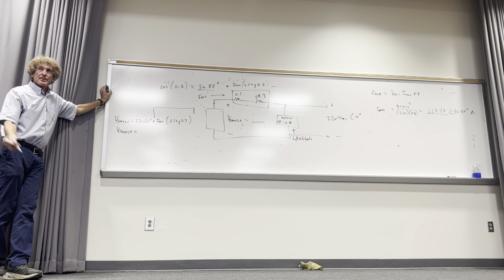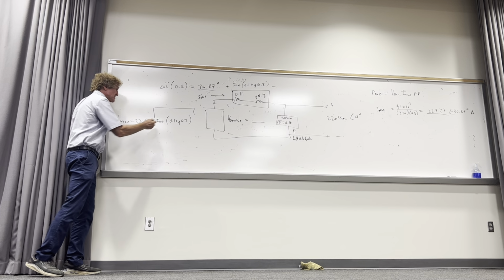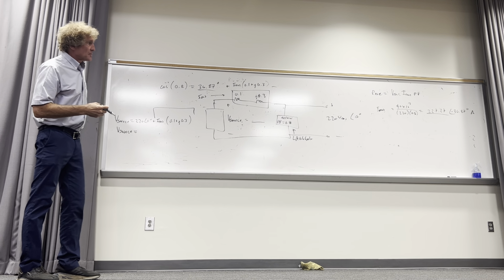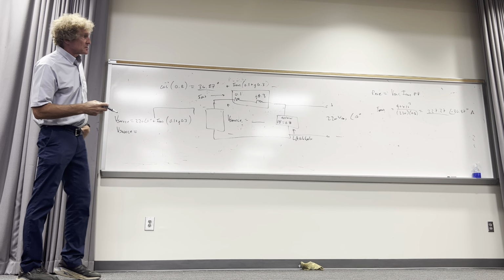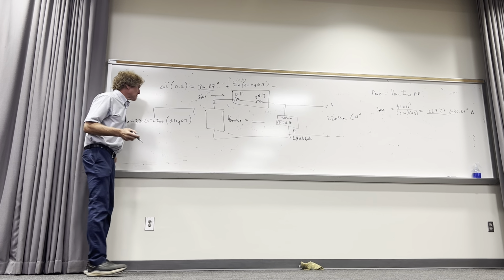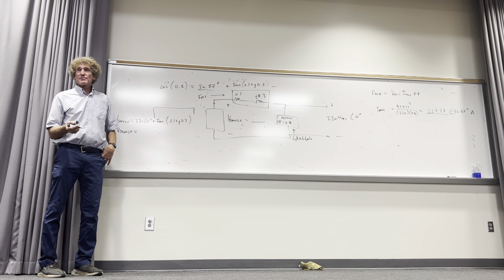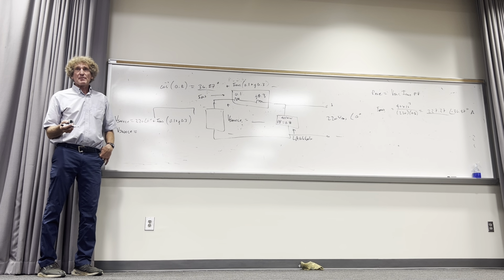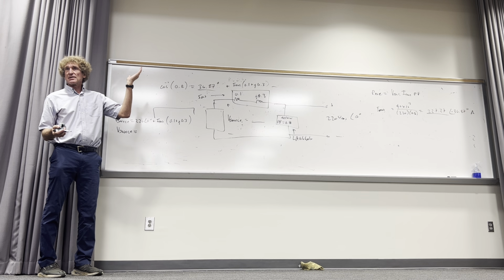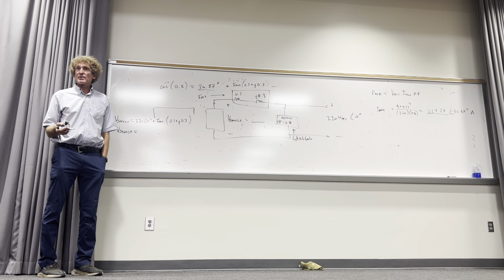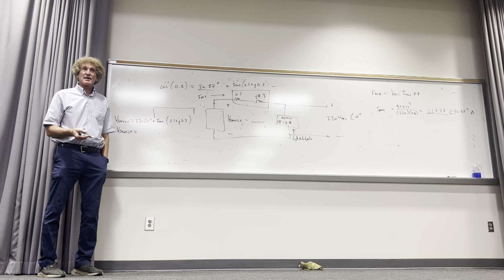And gentlemen, you got a different number before? Let's see if he gets the right numbers. I'm making sure. So what do we get? If you just take I_RMS, which is 227.27 at minus 36.87 degrees, times 0.1 plus j0.3, what do you get? Magnitude and angle, if you don't mind. Go ahead and try it. I really am trying to help you. How many have made mistakes in your calculators doing calculations for tests? A lot of that happens. And it happens in a way that really irritates you because it's so obvious you made a mistake when you look back.